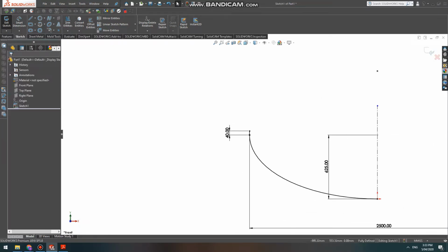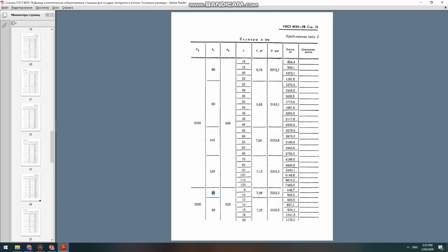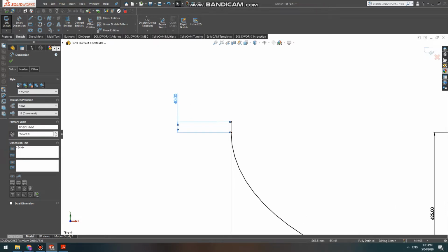40 millimeters, it's good. Yeah, it's standard, it's good to use it. However, in production you may face problems, and as I explained the last class, if you take 40 millimeters for this part, in production it becomes non-homogeneous. So at some part it will be 20 millimeters, at some part it will be 60 millimeters.